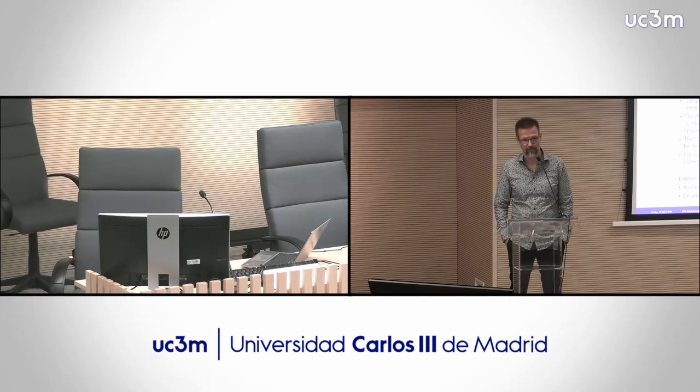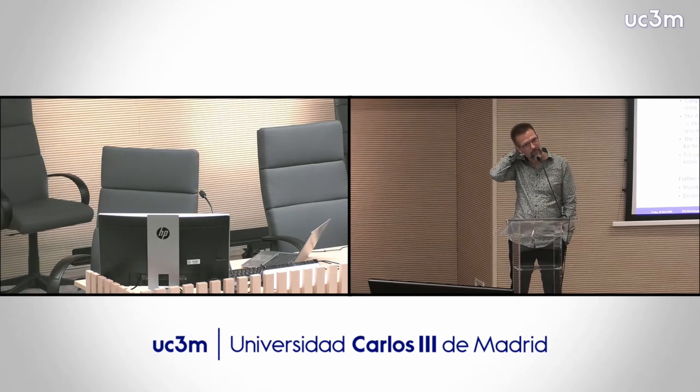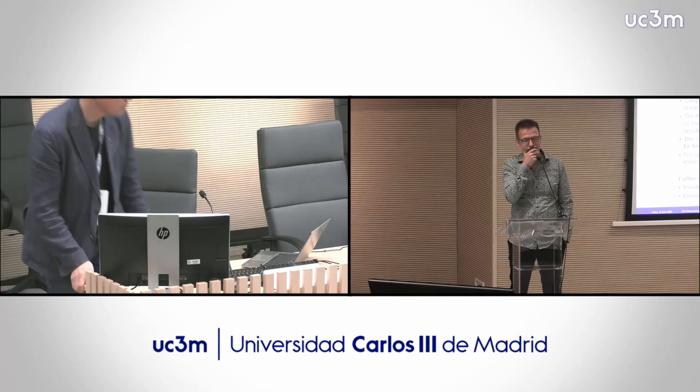Thank you, Mike. Very interesting. My suggestion is that when you have the lifting line, by the way, we have also done with Jean-Baptiste models where we use the lifting line, which, as you know, has the difficulty that from the trailing edge to infinity, you have these straight vortices. And you would like to have them more complex, like helical. So at the end of the day, when you want to put a lifting line in the CFD solver, where you can have very complex wakes, like what we do for wind turbines, you come to the conclusion that the lifting line becomes an actuator line method in the CFD solver.